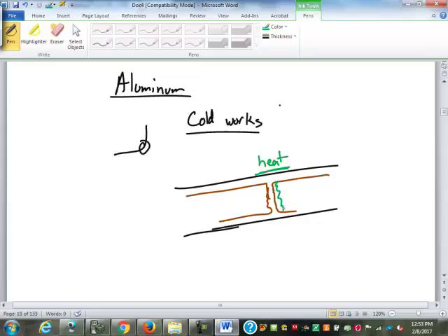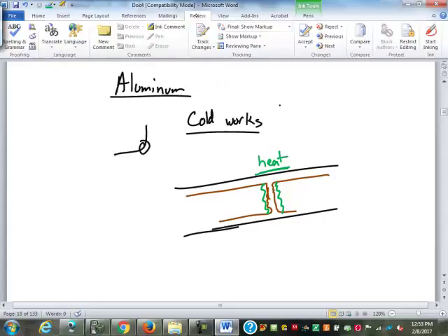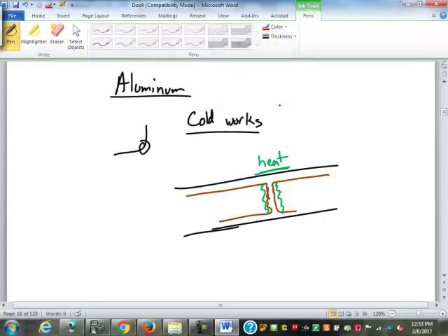So as the surfaces of this got hard and brittle, the spark jumping would actually cause chunks of the metal to chip off. And it actually just crunched this up, and it almost became like little stones inside that wire. It almost powderized the wire. So that now it's really jumping, and eventually that got to where that spark, the further a spark has to jump, the hotter it is. So it got to where finally that spark was jumping far enough to create enough heat that it caused a lot of fires. To the point where insurance companies no longer will insure a home that has aluminum wiring in it.